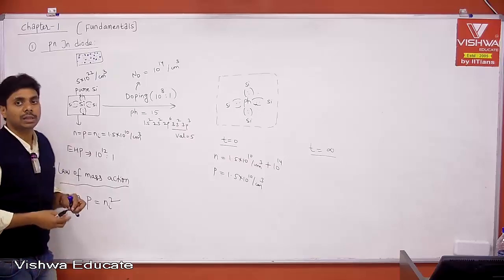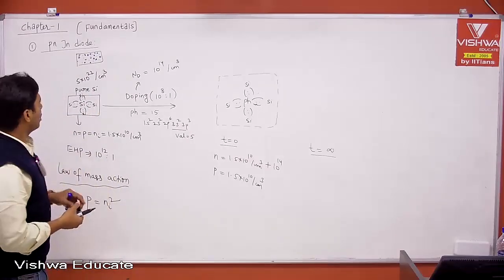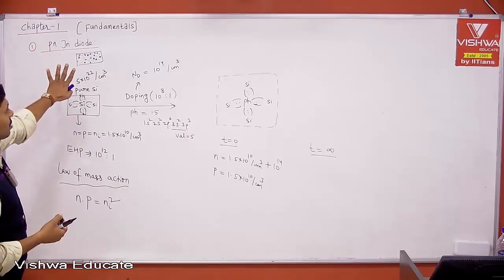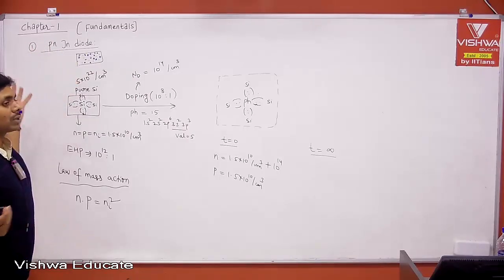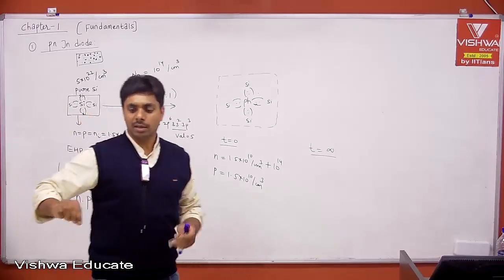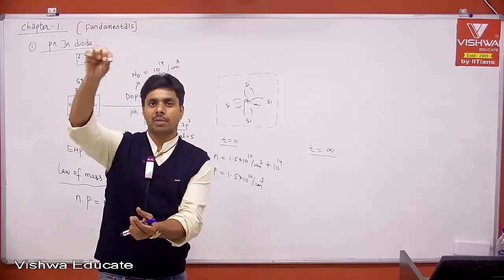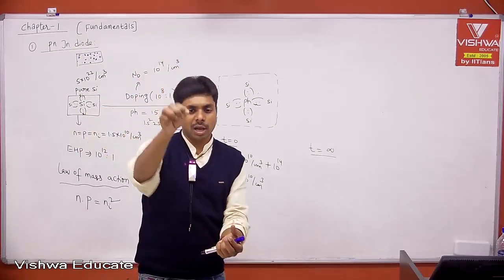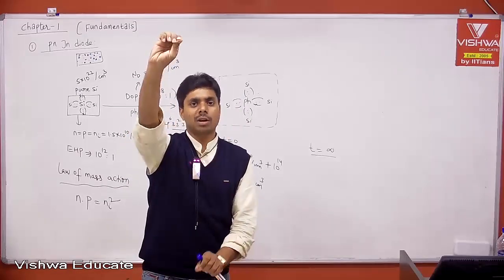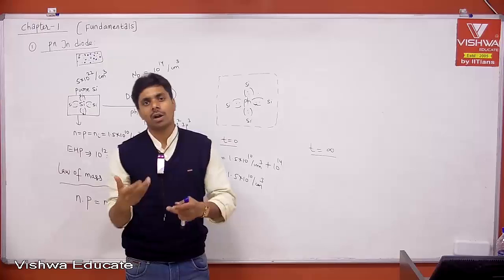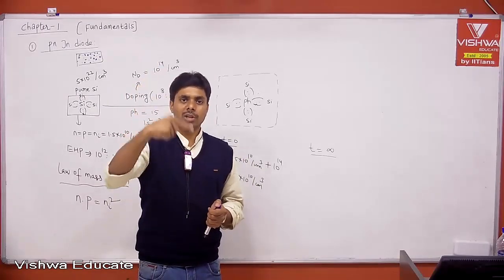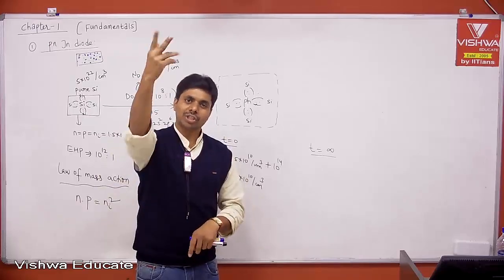This is what is called thermal equilibrium. At thermal equilibrium, if you see from outside how many electrons are there, those many holes are there, and that is your intrinsic carrier concentration, but the same electron will not be there throughout. What I mean is, let us say this is the hole and an electron. After some time, due to collisions and all, the electron comes back and recombines with one of the holes. At the same time one more bond will be broken, and then you will get one electron and one hole. Therefore, that is what is called the equilibrium state. Recombination, at the same time regeneration. Recombination is due to temperature, regeneration is due to temperature.